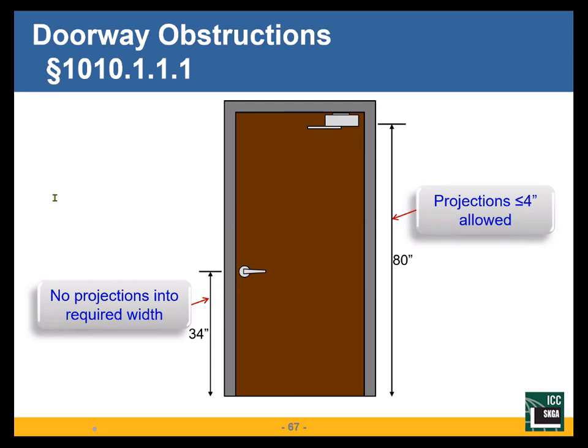In my net floor area requirement, I exclude the restrooms. And I'm making the assumption that the people in the restroom are people that were in the other areas of the building. So the occupant load didn't change. They just have moved into another area of the building.